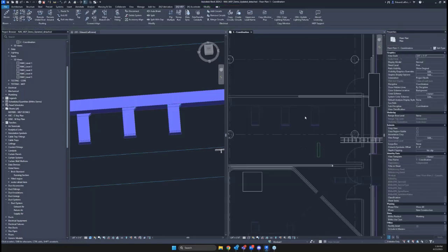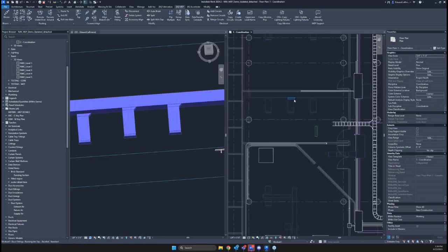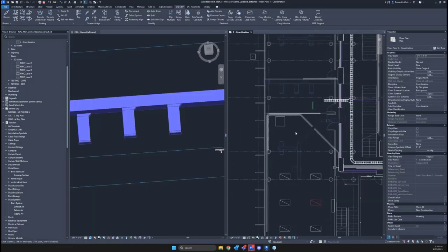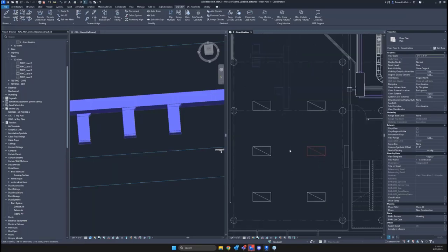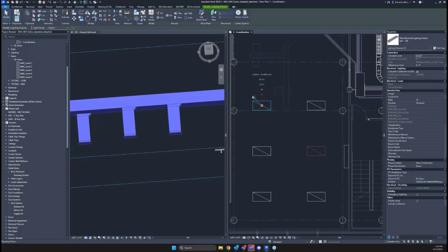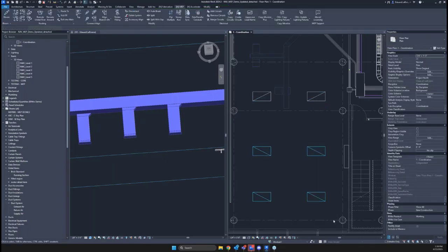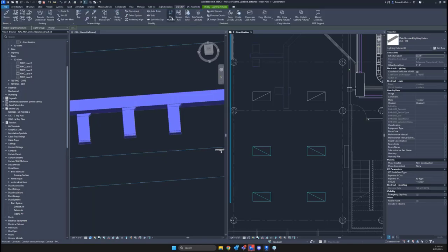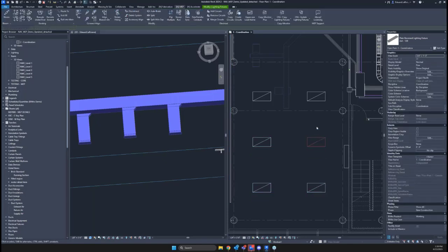So flip multiple is a lot more powerful than just flipping boots. It's a flipping great command. So what else could we flip? Maybe some lights. This tool actually came out because I placed about 2,000 lights on the wrong work plane, and I had to spend 2 days flipping every flipping light to be the correct direction. So instead of clicking this button 100 times, grab all of your lights, jump up to MEP and use flip multiple to flip them all. Incredibly quick way to make your way through here.